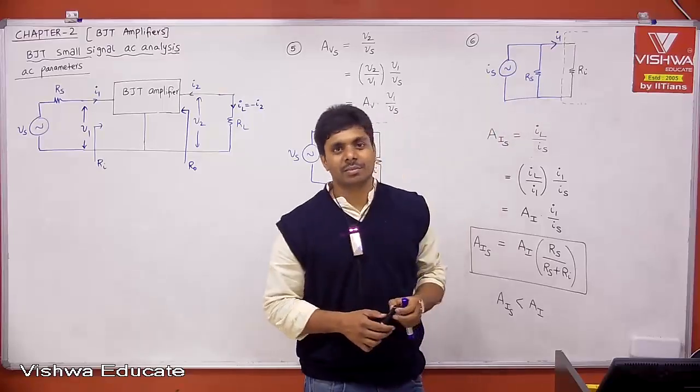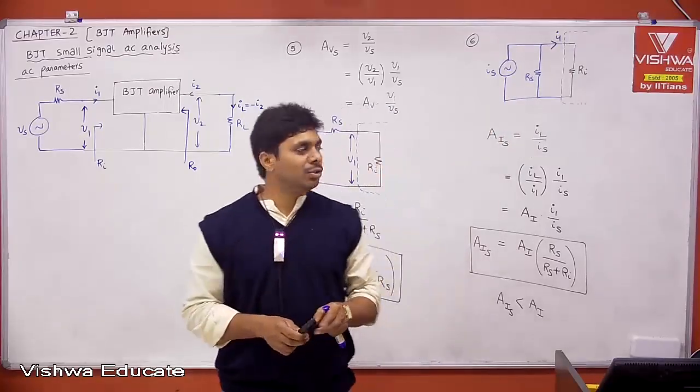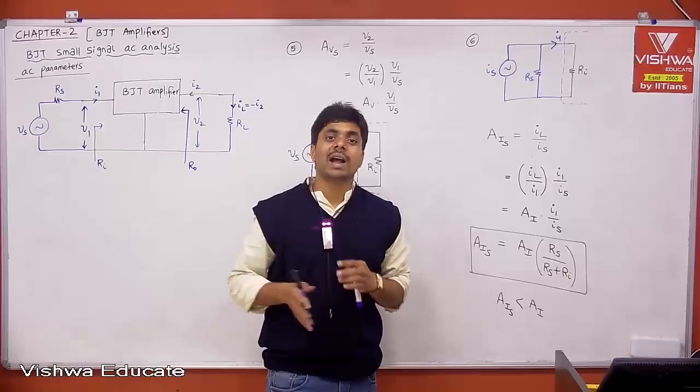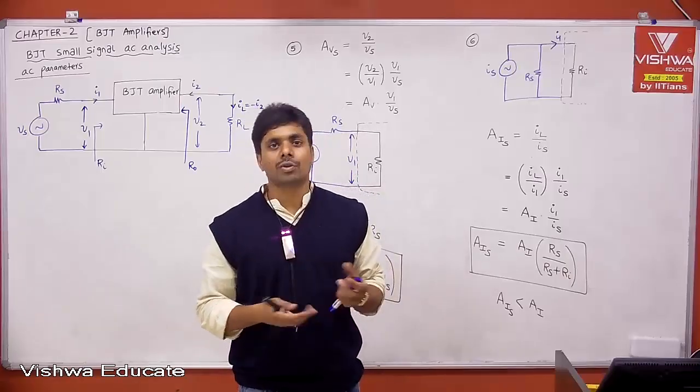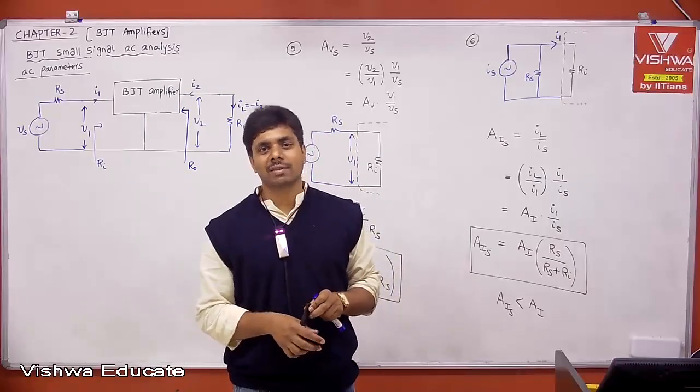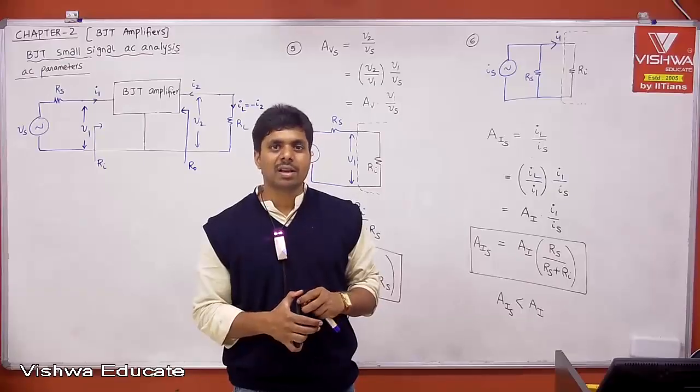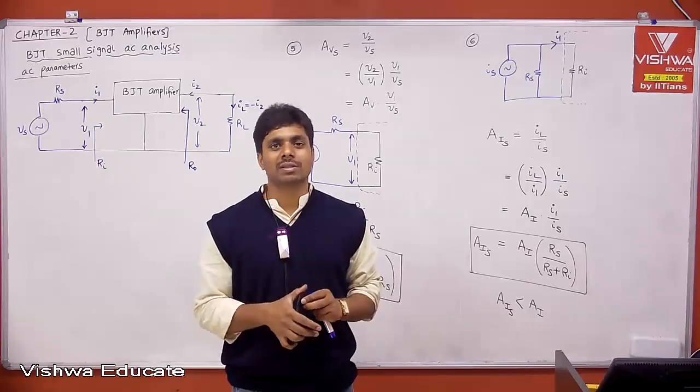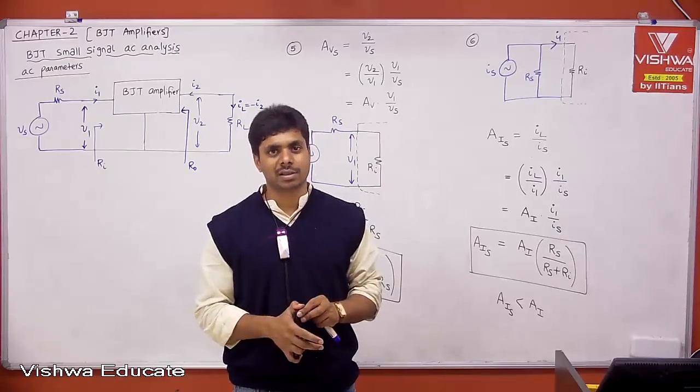Ideal current source. But what is the guarantee that you will excite your amplifier with an ideal current source? We don't have ideal current sources. Definitely we have some source resistance. Then we have to excite with practical current sources, and only then does it match the practical analysis.